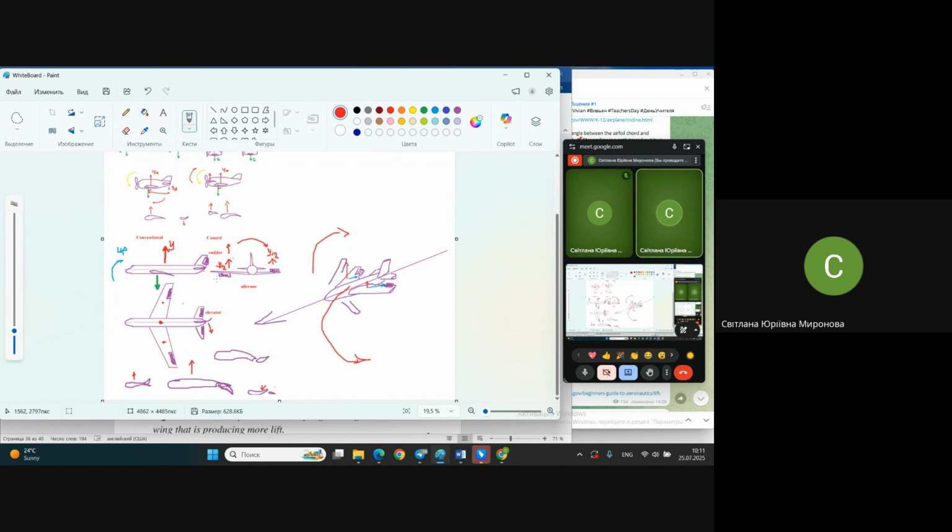on the wing. What do I mean? That ailerons are used not only for rolling. They may be used for this complex, not so direct motion as when you're using the rudder, but it may be used for yawing also. Ailerons are moved for rolling, and ailerons may be used for yawing, because using ailerons will result in distortion, let's say, of the trajectory of airplane flight.